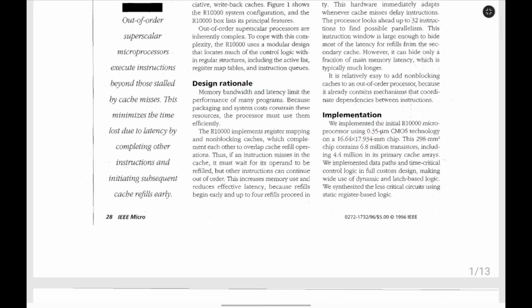Memory bandwidth and latency limit the performance of many programs. Because packaging and system costs constrain these resources, the processor must use them efficiently. The R10000 implements register mapping and a non-blocking cache, which complement each other to overlap cache refill operations. Thus, if an instruction misses in the cache,